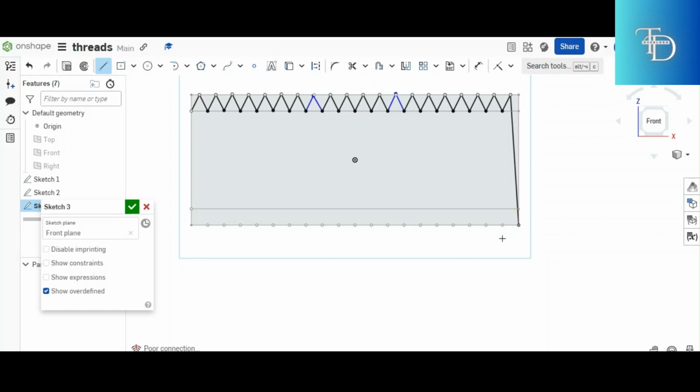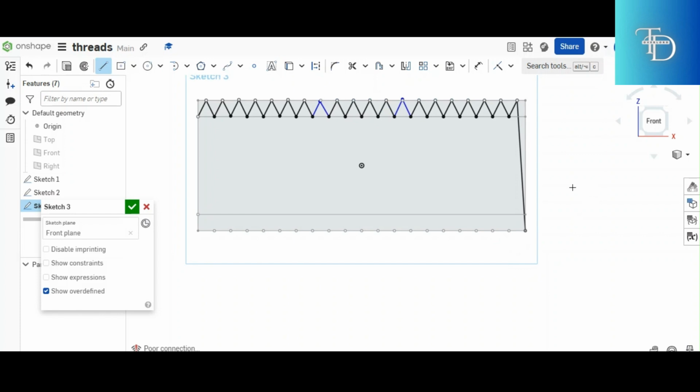You go to the opposite side, right there. There's nothing new, there's nothing different. You do the same thing that we've been doing on the top side. So you create the V's with a 60-degree angle. You take your ruler, you mark 60, and then you do the very same thing for the other side, for the opposite side right there.